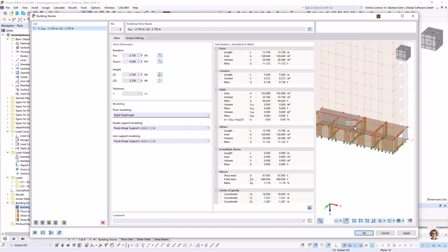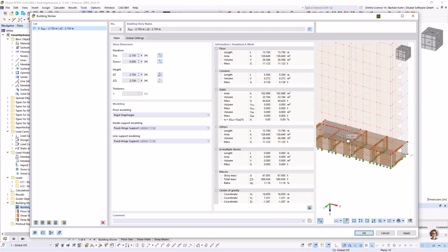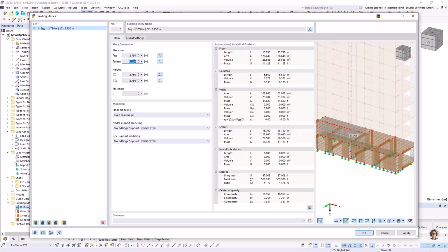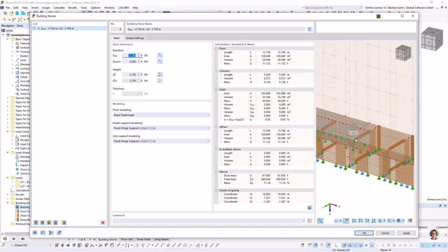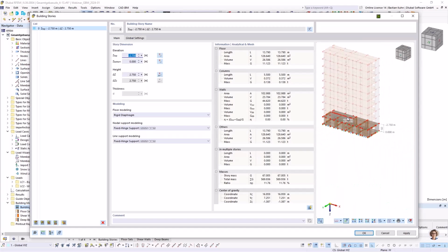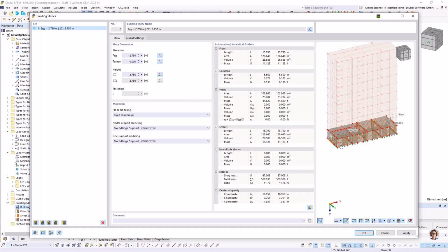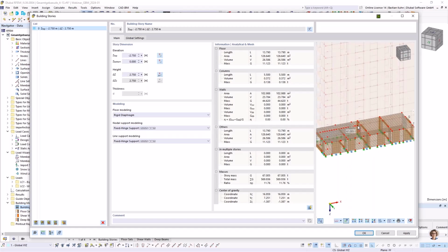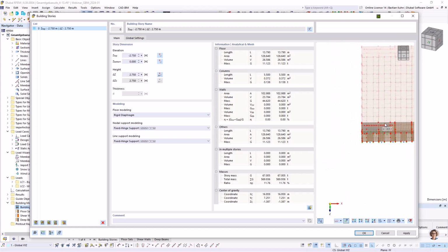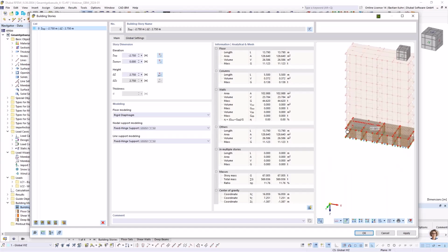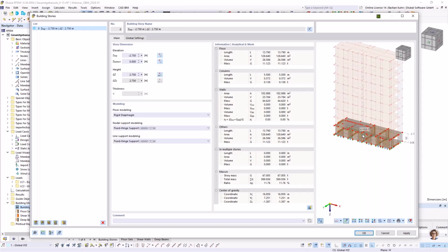Yeah, so the first story is already there. You see the software knows it is located the first story from the origin 0 to minus 2.75. I can always choose any level elevation that I want. I get a mass. I get also a mass center. Obviously, where I'm having the concrete kernel, I have more mass, and that's why the mass center point is moved a little bit to the left side here, and afterwards it will also calculate us a stiffness center of the complete structure.